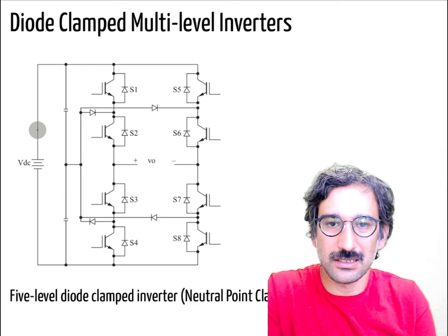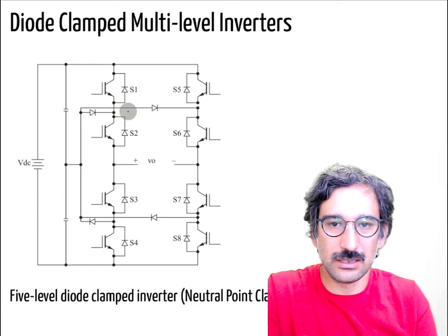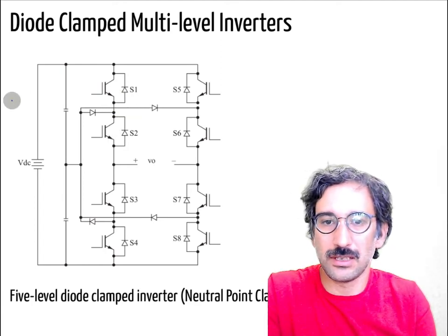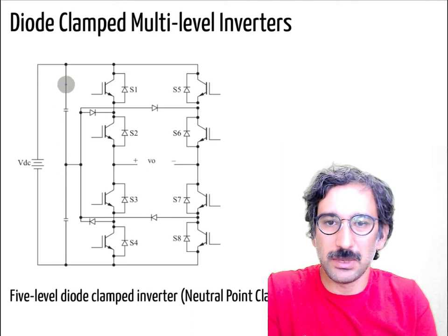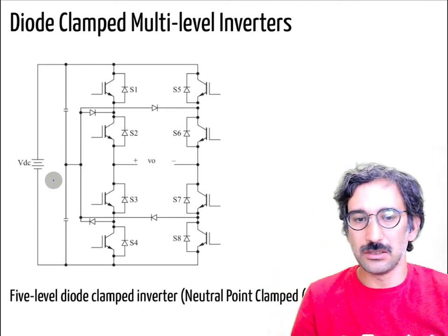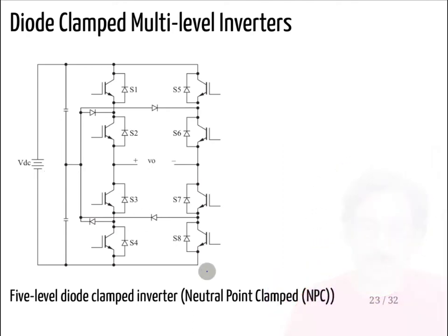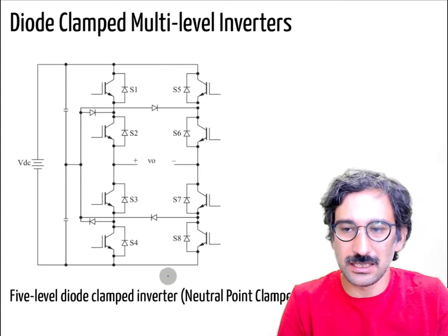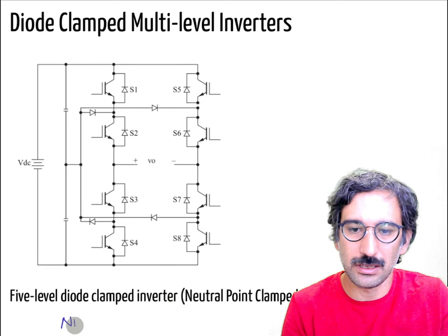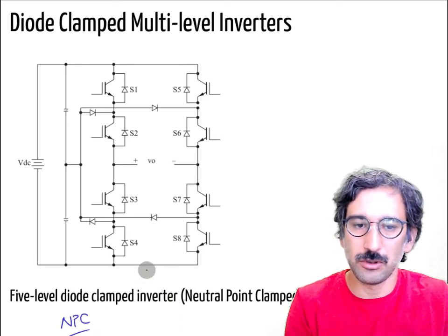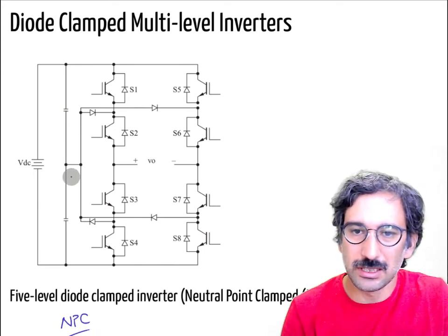Another interesting point is that it is not just two series transistors. I divided my DC voltage into half. So this is called the neutral point clamped, NPC, neutral point clamped multi-level inverters.